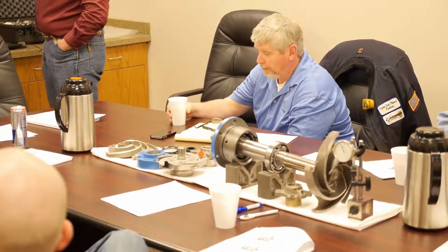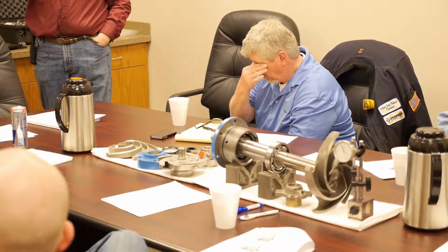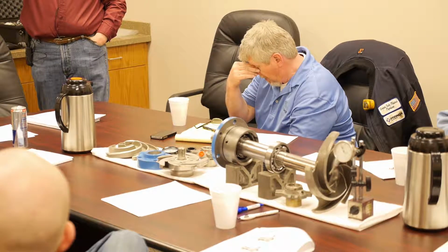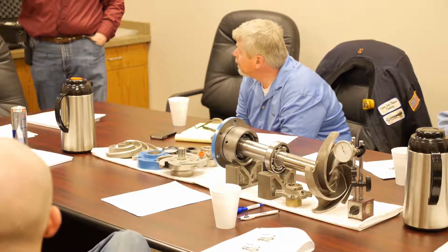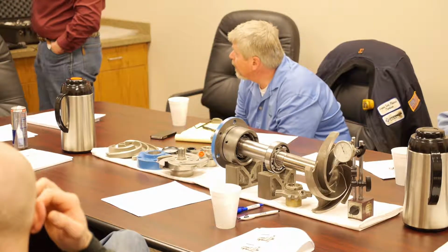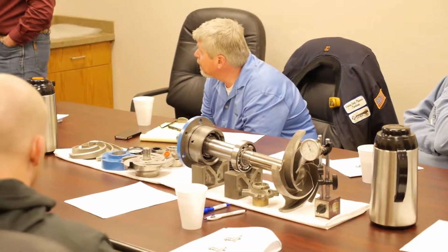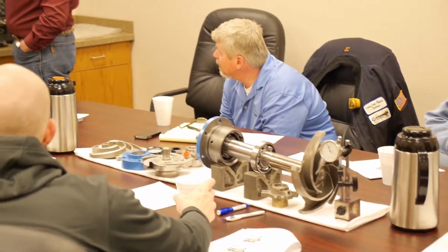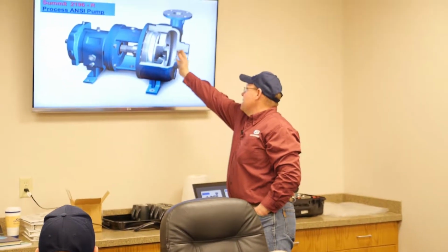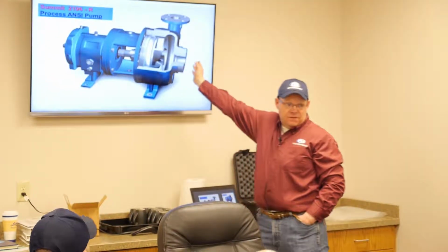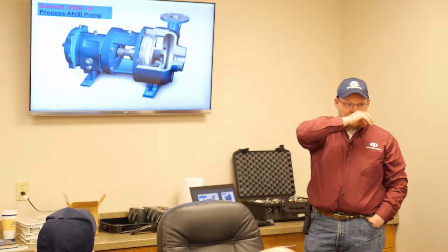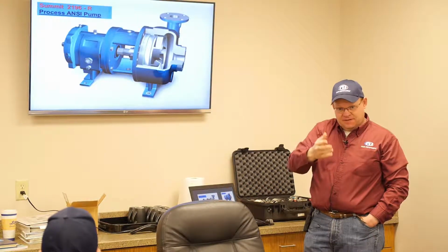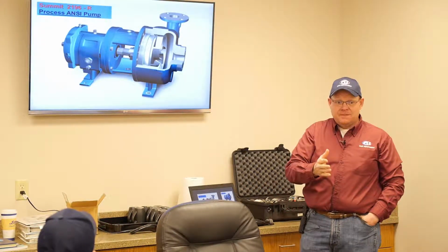And again, I'm going to show you some different variations in centrifugal pumps so that you get a better understanding of what the difference between ANSI and some of these are. This is what we call an ANSI R. If you notice, see how far this impeller is back from the front of the volute? What do you think that might be used for? Solids. Very good, solids. Recessed impeller.